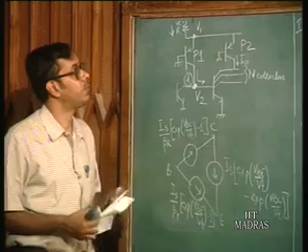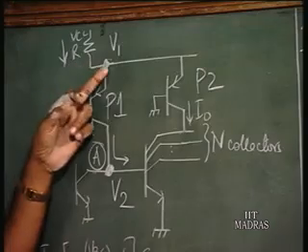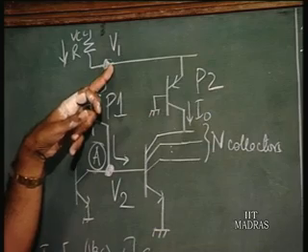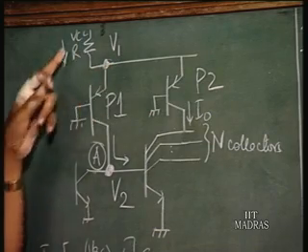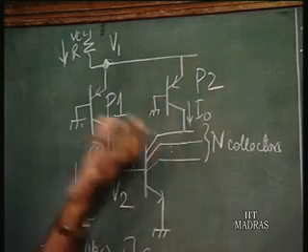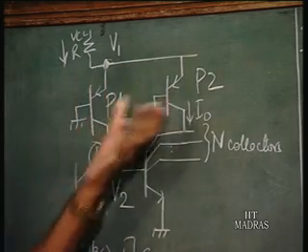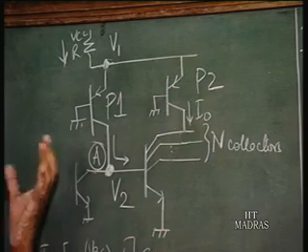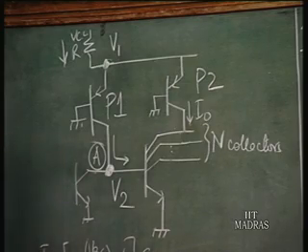So, if you increase the current flowing into the cell, that is if you reduce R, because this voltage is around 0.7 to 0.8 volts, you have larger current, which would mean that there is going to be a proportional increase of current flowing through the individual injectors. So, that is going to improve the noise margin.